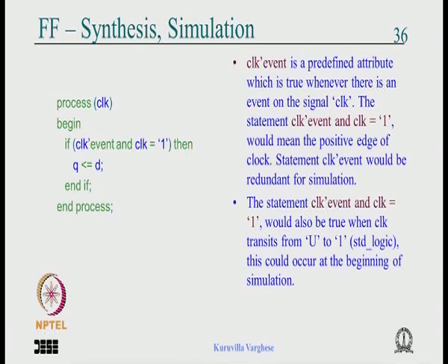There is no harm writing the code like that, but when you simulate, make sure that the behavior of the simulation and the behavior of the real circuit is identical, particularly with initialization and mis-trigger and all that, so that you get what you are hoping and expecting. Otherwise, you may think you know the behavior properly, but you don't know why it happens in simulation.